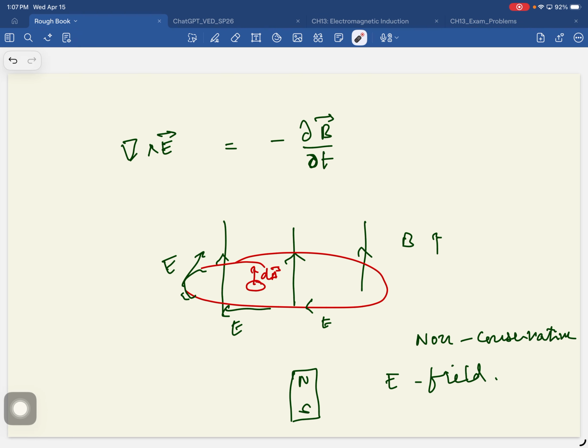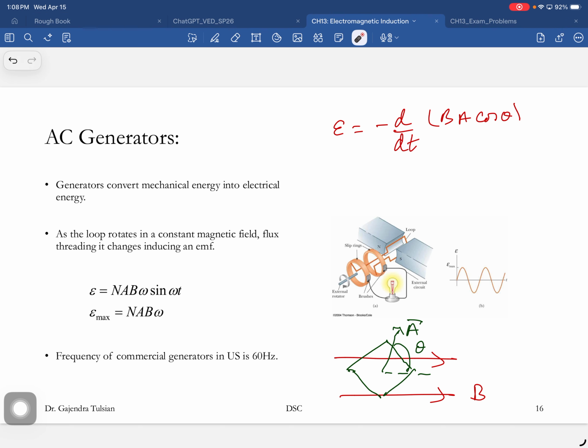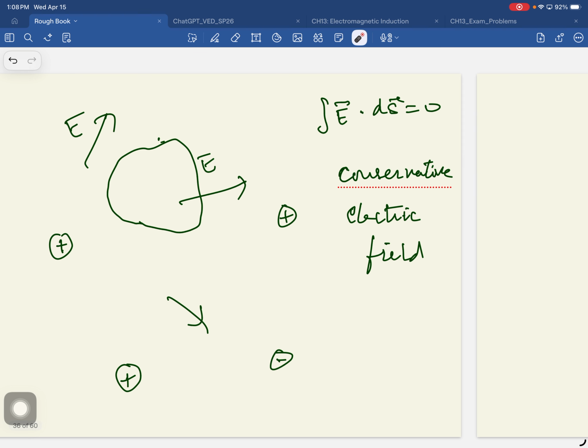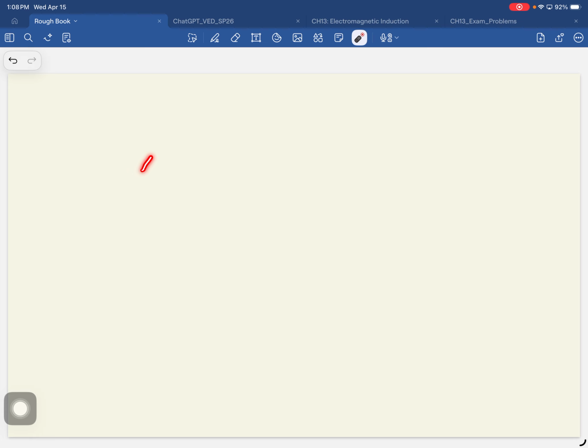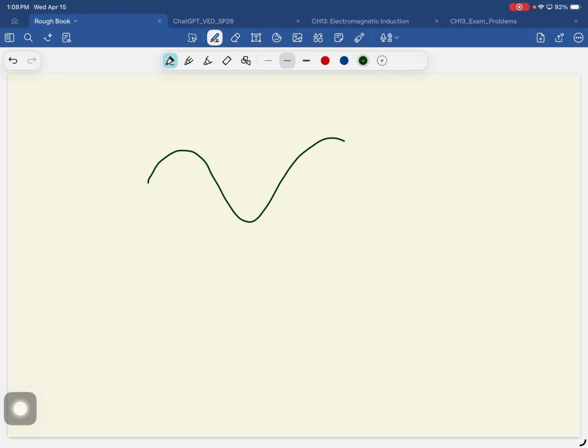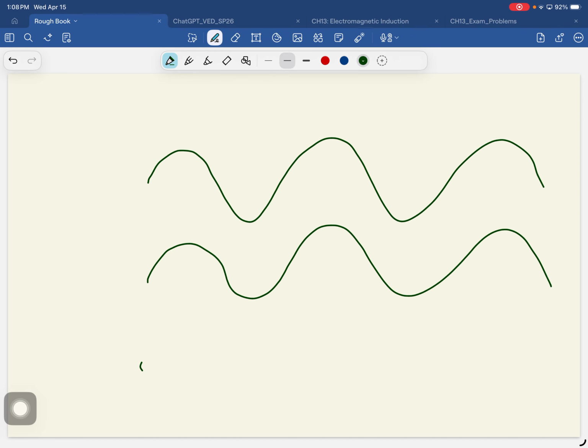Each one of them, as they rotate, is producing a waveform like this, and then you have to feed it to the grid. You rotate them at different speeds. Anyway, eventually when you feed the signal to the grid, every one of them has to be 60 hertz, and you have to feed the signal in phase. Everyone has to feed them in phase.